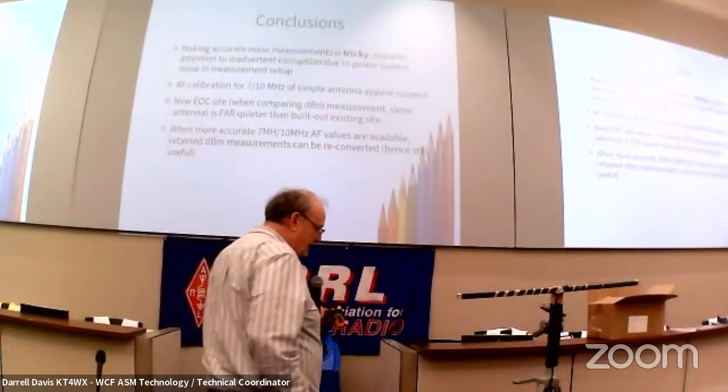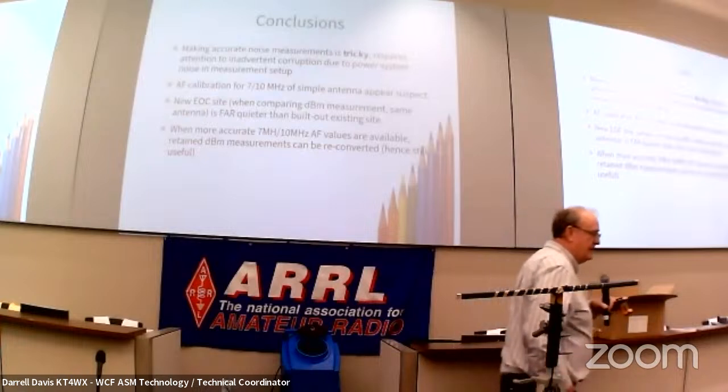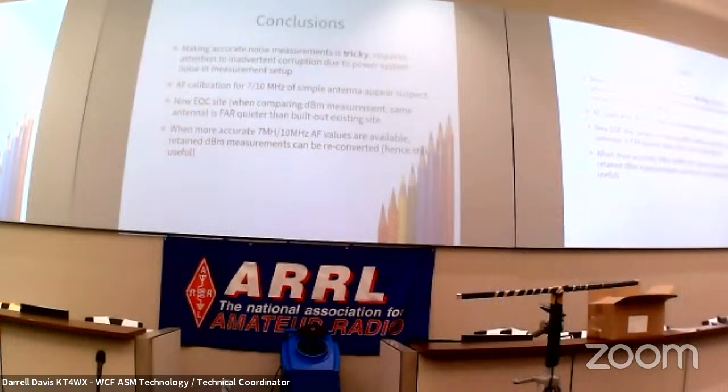Okay, so I know noise is something that hams deal with a lot, but from an engineering perspective, it's not something that we deal with a lot. And the concepts of white noise, the concepts of dB microvolts per meter, all these fancy ways of measuring stuff is a little bit foreign to ham radio operators who are used to thinking in terms of S meters, which are unreliable. I made measurements on my S meter and it was 3 dB per S unit, not 6, like it's supposed to be. And I published that in one of our papers.